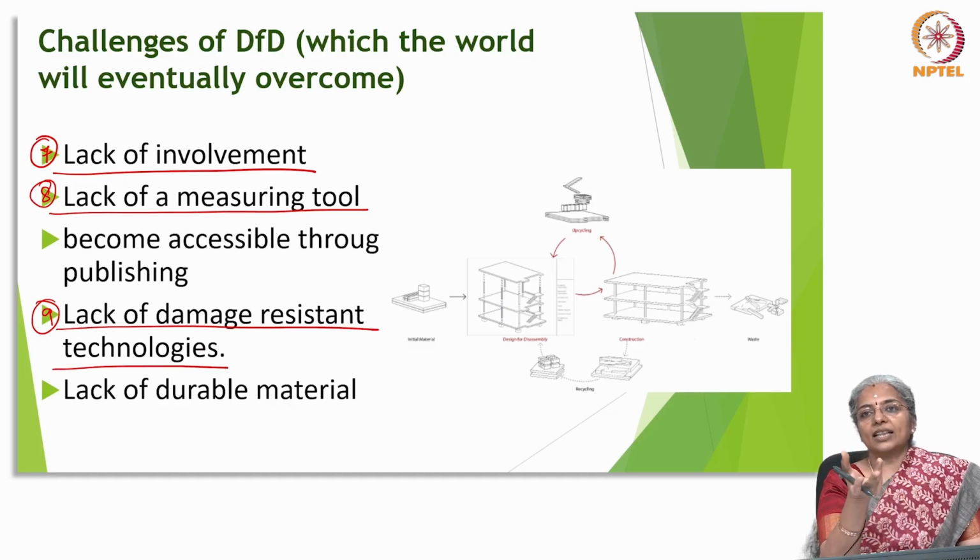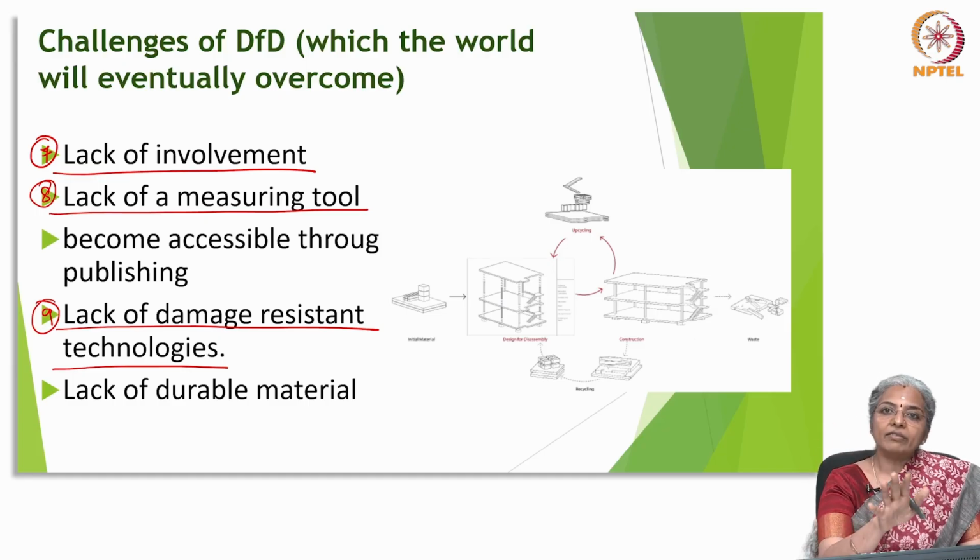So, the other challenge that appears when designing, say, a concrete building for disassembly is the suitability of dry connections for certain important areas like seismic resistant areas, since the ductility and the dissipation in frames and structures are required to resist the drift and the movement of earthquakes. But we can definitely overcome this with damage resistant technologies.